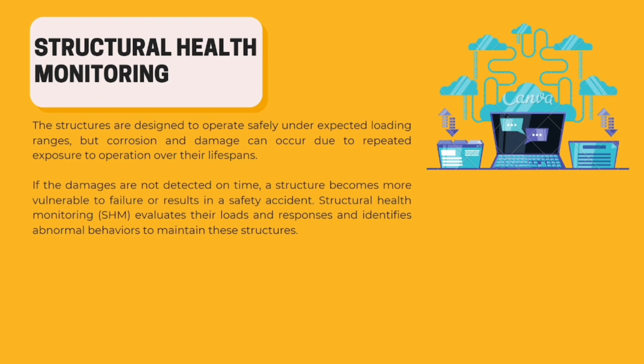Here is structural health monitoring. This is also a very important domain that can use time series analysis. Basically, it studies the damage and corrosion that can occur on structural establishments like bridges, roads, buildings, etc. So structural health monitoring basically detects the loads and responses and identifies the abnormal behaviors of these structures, and it can predict the upcoming damages or upcoming maintenance if they are required, and what is the expected lifespan of such structures.